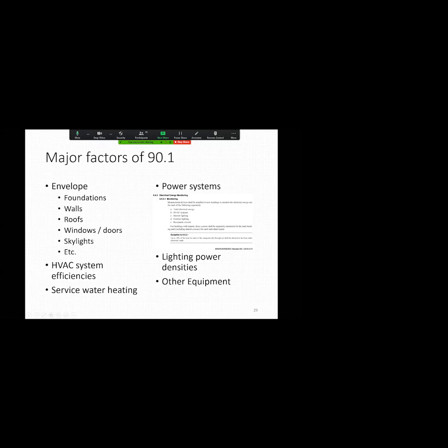So when you have all of that extra heat production in a commercial building because of these loads, the envelope is not going to matter quite as much as it does in residential, where you don't have all that excess heat generation in your home. And so the envelope is going to make more of a difference in your house than it's going to in commercial buildings. But we always want to produce as good of an envelope as we can, because otherwise you're potentially going to be using more energy than you need to.